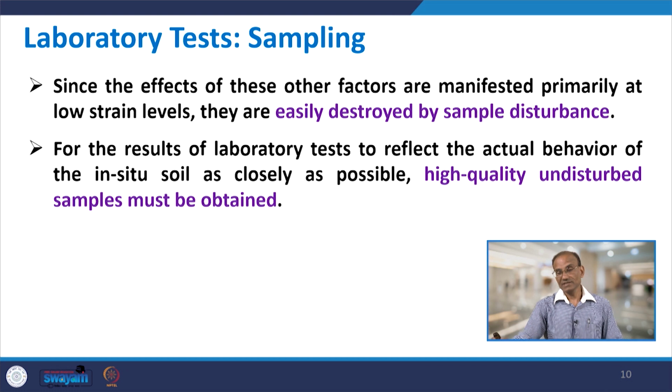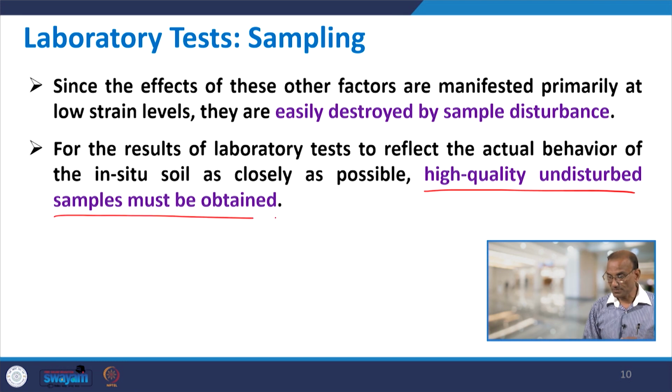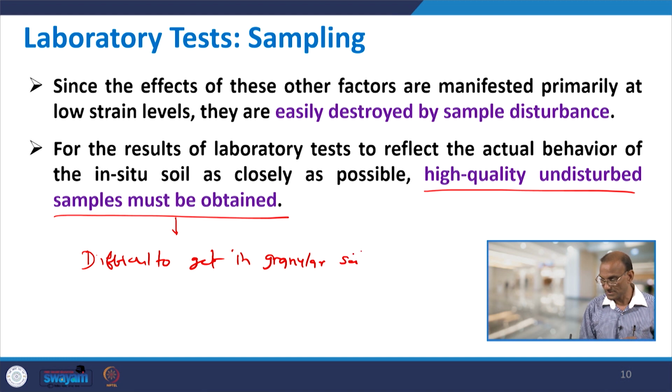But this is the requirement, that you get high quality undisturbed samples. This may be difficult to get, or even sometimes impossible to get, for sand, that is, granular soils, or what we say in short sand. It may be okay in the clay.